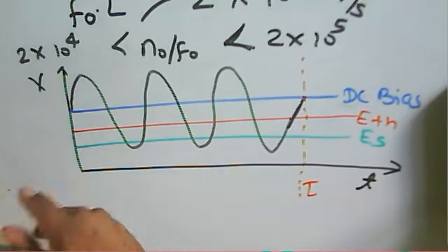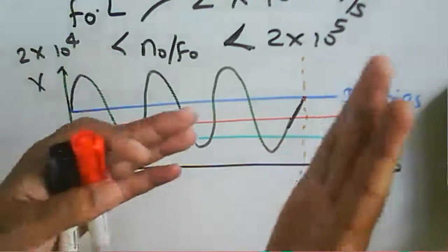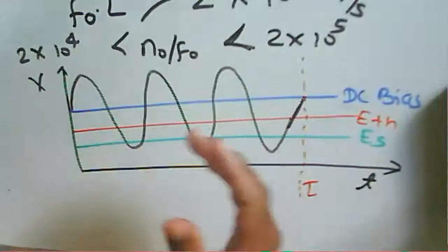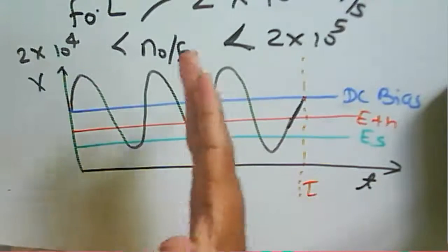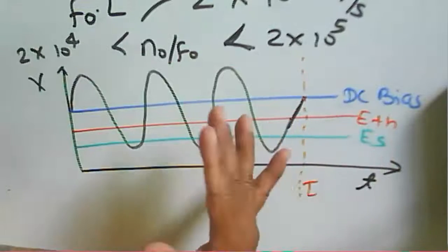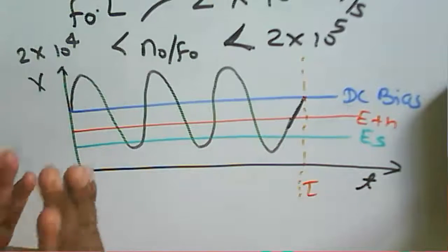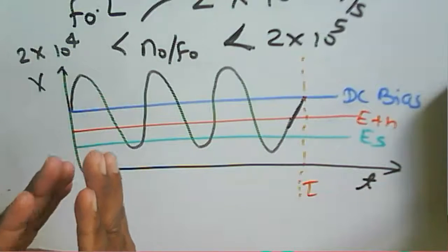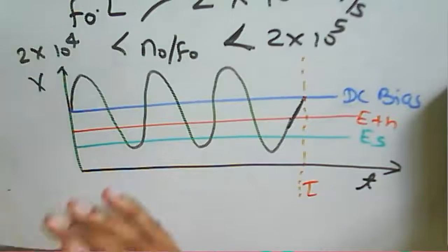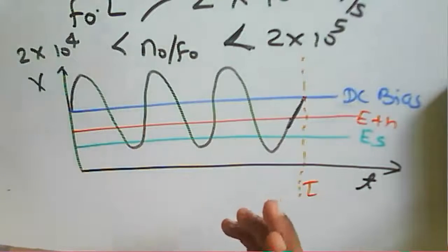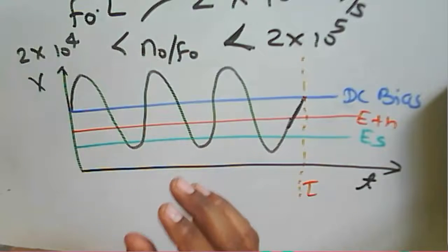Domain collapse means the domain is collected at the anode. In the LSA mode, the frequency of oscillation does not depend on the transit time. It depends on the resonant circuit that is used.